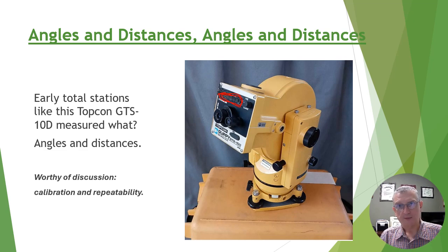Surveyors still need to be able to do a brief explanation of how the beam is transmitted from the EDM, how it hits a prismatic mirror, and returns back the same path due to the modulation in the wavelength. The EDM is able to count the wavelengths, know how long the beam was gone, divide that by the speed of light, and you have the distance. Simple physics 1.